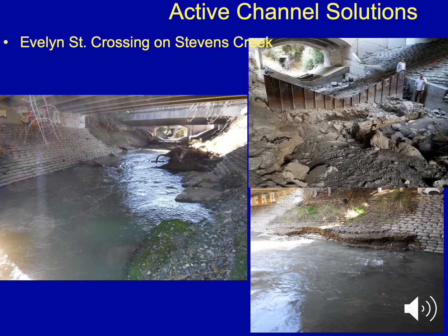At construction, these things were completely buried in sediment. There was about 6 feet deep of engineered stream bed material, which is just a fancy word for calculating the size distribution of the sediment you're using in a design. So we had about 6 feet of sediment at the edge, a trapezoidal shape to the channel. Here, these pictures are at about 50 CFS, which is actually a little lower than the active channel width. You can see the water up to the last little bit of sediment that is left.